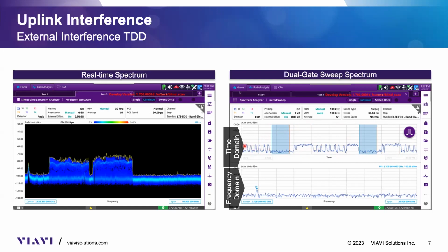As you can see, we have a good distinction between the active slots and the slots that are quiet. This is because these are downlink, uplink, downlink, uplink, and so on. In LTE, the way in which those slots were assigned between downlink and uplink is based on a subframe, so every 1 millisecond you can make that transition.